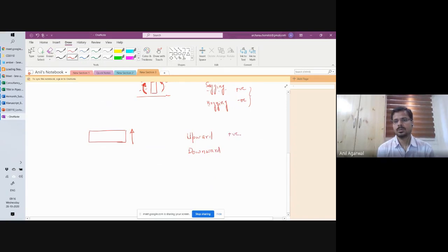Okay. You can call it positive, you can call it negative. Your call. But if I am given this situation, then basically what it means is that one upward force, one downward force, both are acting simultaneously. Then the sign convention would be whether this couple of balanced forces make the object rotate in clockwise direction or anti-clockwise direction. So your sign convention could be that this one I will call positive if it is making it go in the counterclockwise direction.